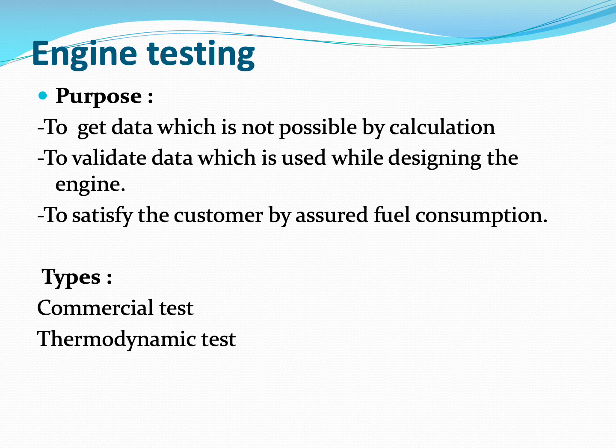Next, let's move to the next topic, engine testing. The purpose of the engine testing is to get data which is not possible by the theoretical calculation. It is also used to validate data which is used while designing the engine. That means whenever the designer designs the engine, they have considered or assumed some of the data and they have calculated some of the results. To validate the assumption and to validate the output of the engine, the testing has to be done.